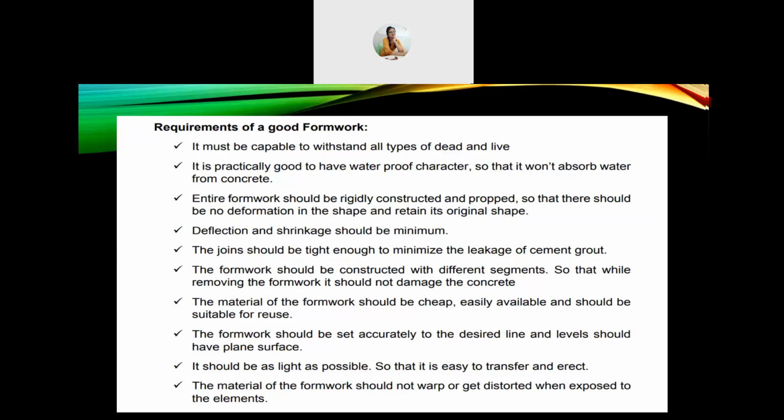Number 8, the formwork should be set accurately to the desired line and level and should have a plain surface. 9, it should be as light as possible so that it is easy to transfer and erect. And last one, number 10, the material of the formwork should not warp or get distorted when exposed to the elements.